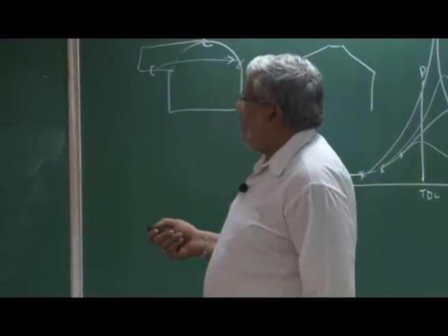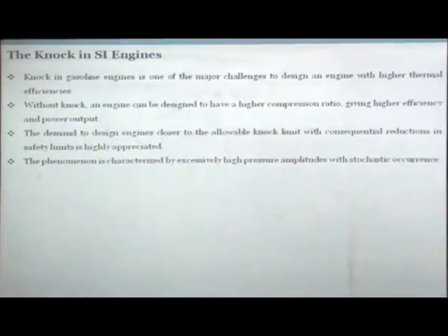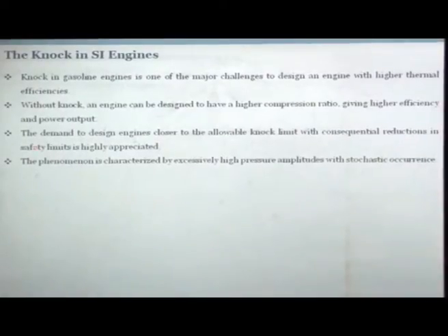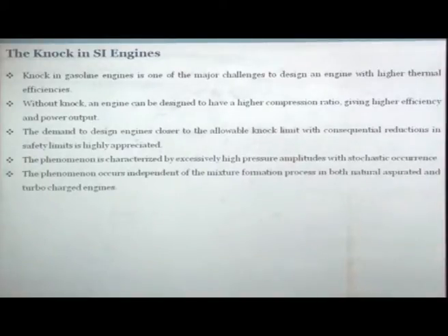Okay, the demand on design engineers to design closer to the allowable knock limit, with consequential reduction in the safety limits, is highly appreciated. The phenomenon is characterized by excessive high pressure amplitudes with stochastic occurrence. The phenomenon occurs independent of the mixture formation process, in both naturally aspirated and turbocharged engines.